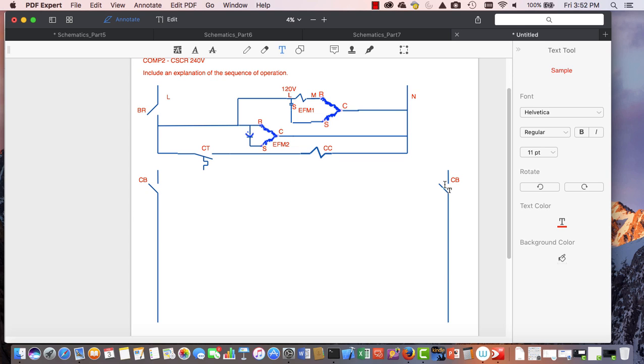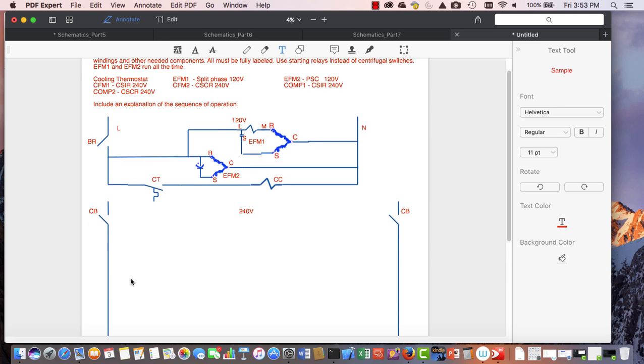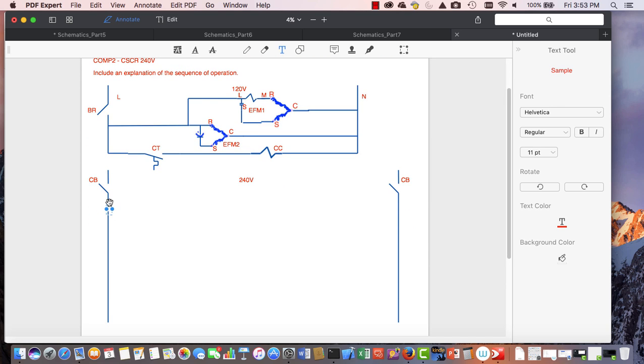Okay, if I wanted to, I could do a dotted line connection between both of these, or some sort of thing to show it's the same thing, that when these go, they'll go together. In this case, I'm not going to, okay? I'm also going to mark this 240 because I want it very clear that this down here is 240 volts. Okay, so now outdoor in our 240 volt unit, I also need a contact.